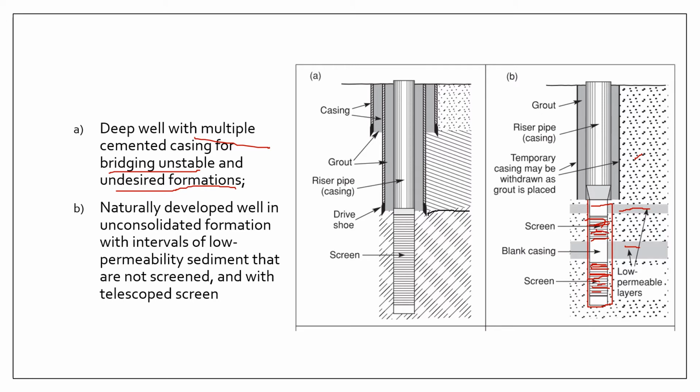First is that low permeability layers like layers of silt and clay contain fines that can end up clogging up your well. Also, these parts may be unstable, especially clays. So in practice it is safest to just screen the water bearing layers in a heterogeneous formation.